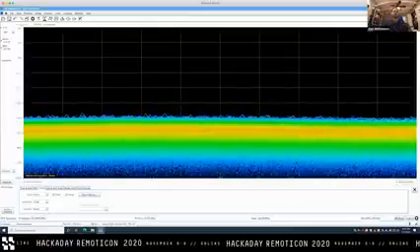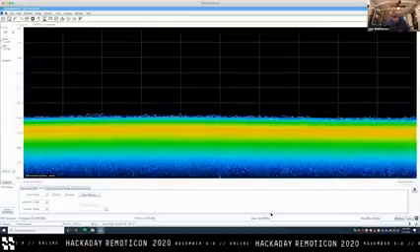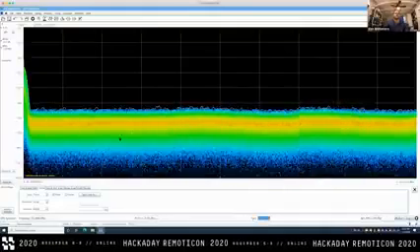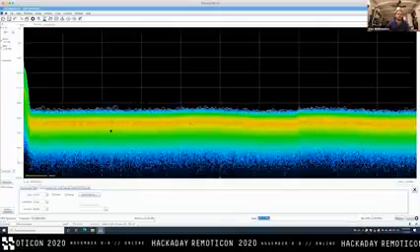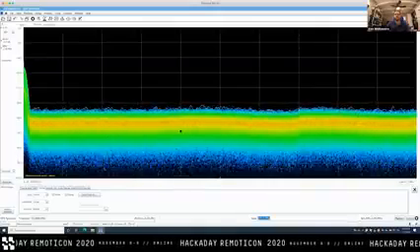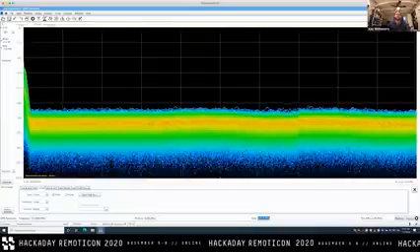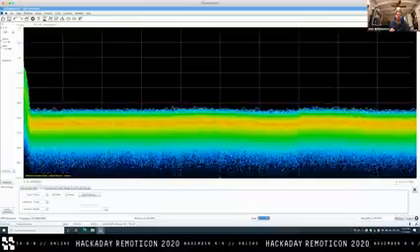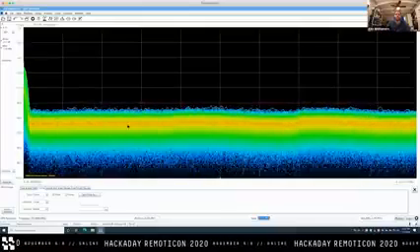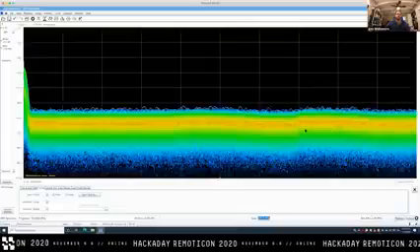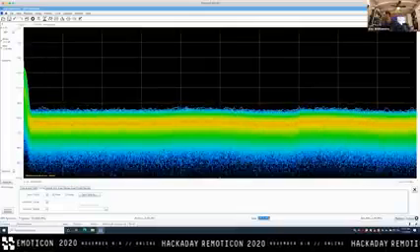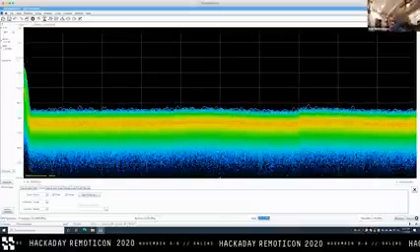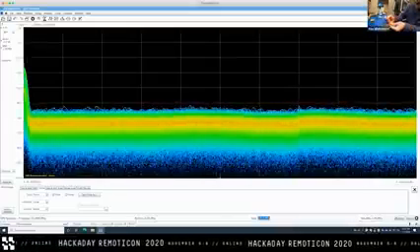If I want frequency 50, span 100. And actually you can see it here where it appears to fill in this part first, then this part, then this part, then this part, then this part, then this part. Because it's trying to capture all that statistical data, so it takes a ton of captures at a particular tuning range and then moves on to the next one and then the next one, we can really see the sort of sweep action that it's doing, and we'll be able to see this later in SDR Angel as well.